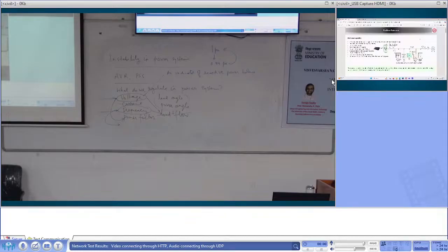What is the one major assumption between voltage and reactive power? That is a very important point. An ideal assumption, meaning there is an assumption we have to make to link voltage with reactive power. Voltage variation does not affect the frequency or load current.